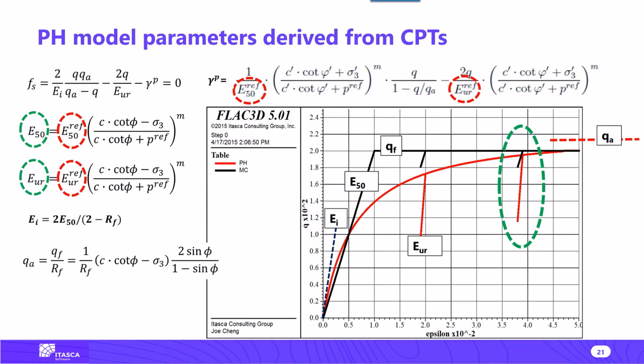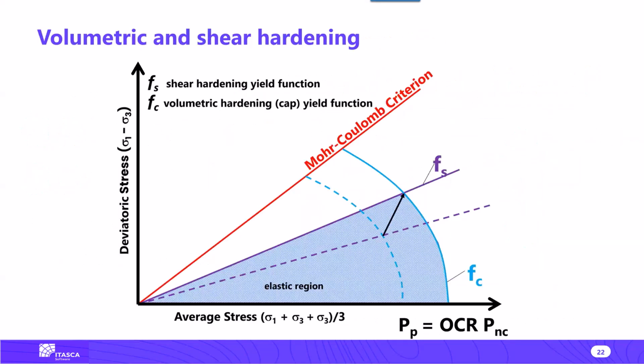There is a relationship of this factor with the soil behavior type. This factor tends to be lower when we have a soil behavior type that is closer to a clay, let's say in the order of 3 to 3.5, and then tends to be higher, 2.5, 3, as a divisor when we are close to a sandy layer, so a behavior type in the order of 1.8, 2, or something like that.